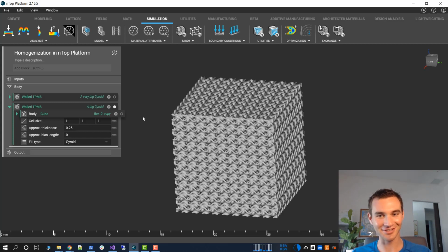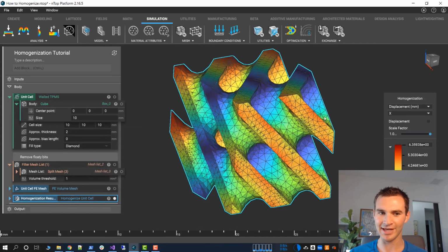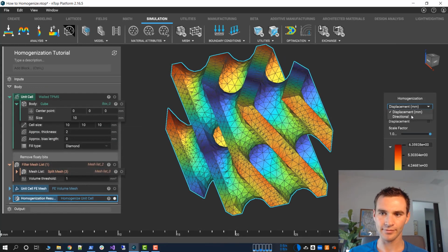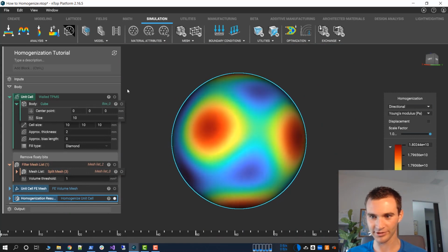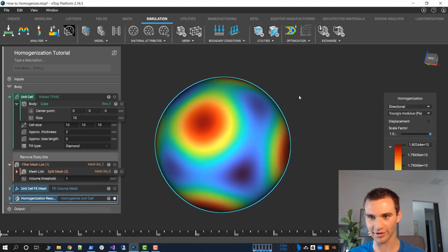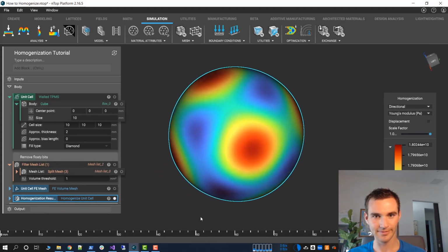But if you were listening to the first part of this video, you're only going to use homogenization to tell you which unit cell is better anyways, not which one is good enough. There is a difference. I can say that a gyroid is better than a diamond unit cell in this case. I can't say whether it's 10% factor of safety on my life critical component. So there is that limitation. Okay, so it looks like diamond is pretty isotropic too. It's nice.